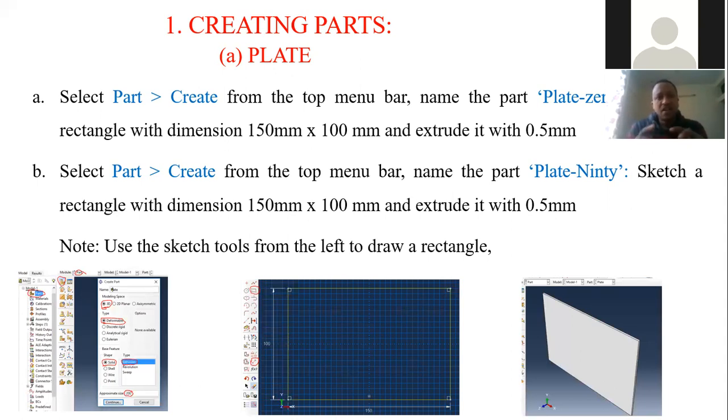But here we are going to stack four laminas together in order to get a laminated plate. So for a laminated plate of 2 millimeter thickness with four stacks, we divide the 2 by 4, that is 0.5 millimeter thickness for each stack, because that means each lamina.